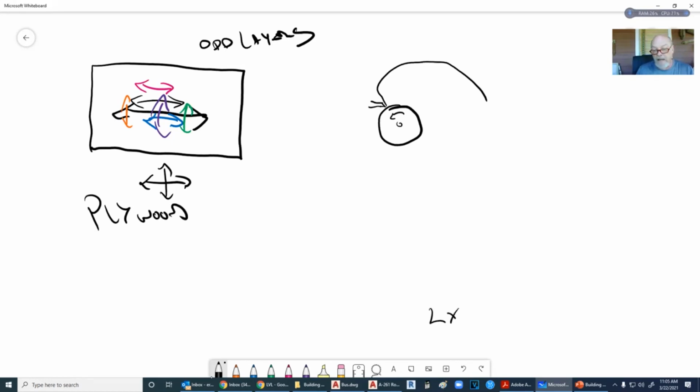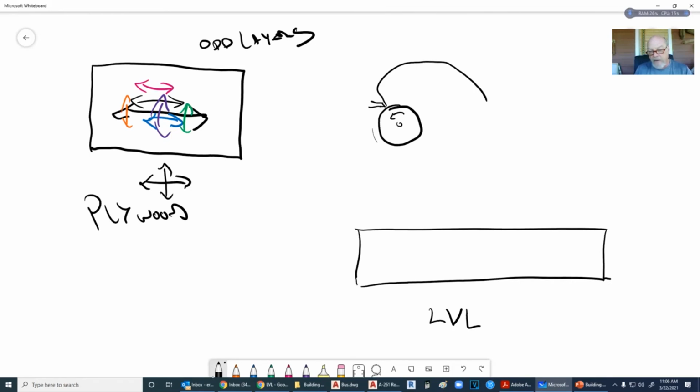So let's talk about an LVL. The same method is being used here. We're taking this tree and rotating it, and we're pulling off a big piece of very thin wood. We put the first ply down in this direction, the second ply down in this direction, the third ply in this direction, and so forth. It doesn't really matter how many plies we have, because they're all going in the same direction. So what does this give us? This gives us a huge, strong, bending motion beam.